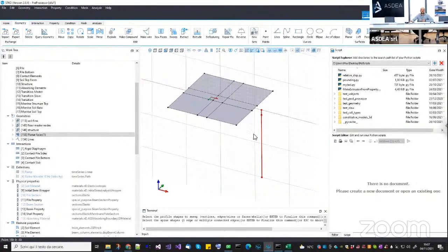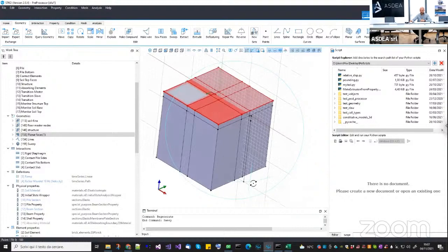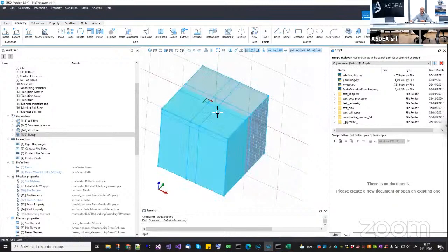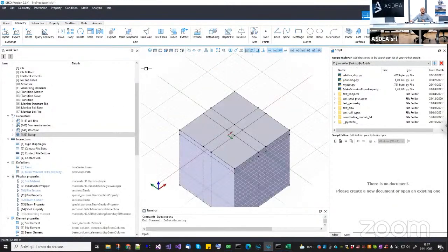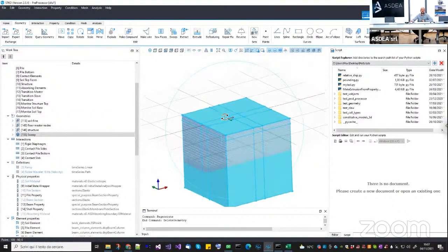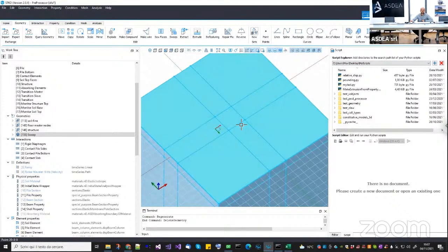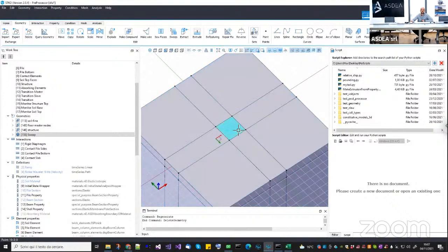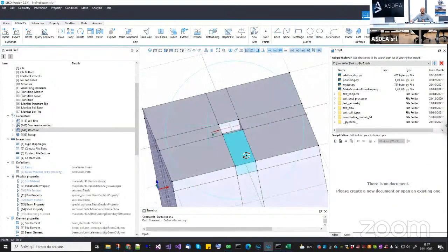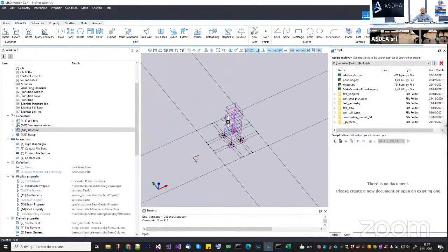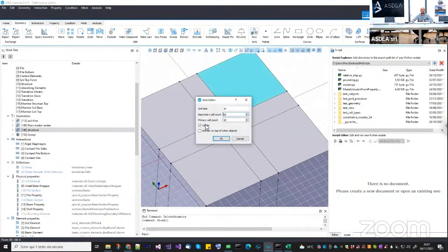Okay, and extrude along this path. Now I can get rid of the generating surface and also of the extrusion path. So what I have now is this sweep here, which is my extended soil domain. And I need to get rid of these central volumes. So I go in sub-selection, I select the solid here and delete, okay? Now basically I have the surrounding domain where I can fit my model, okay? If I show everything, my model is exactly here. Okay, now I want to switch off the grid.